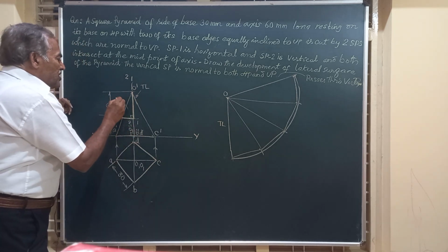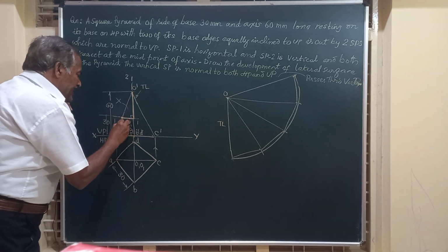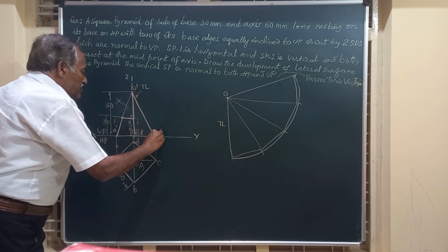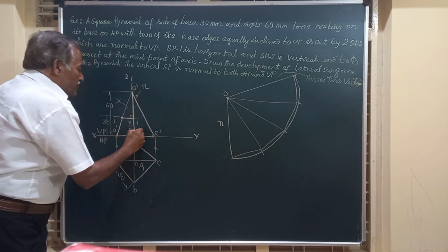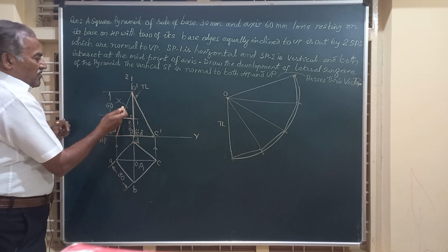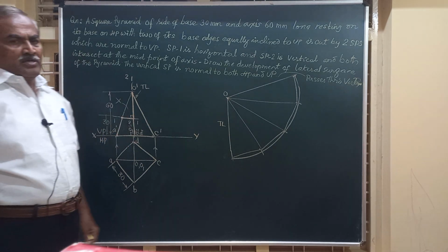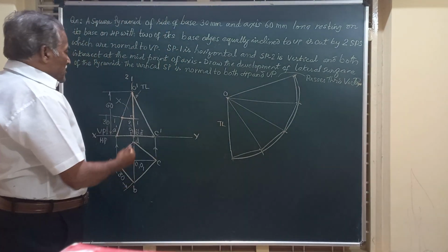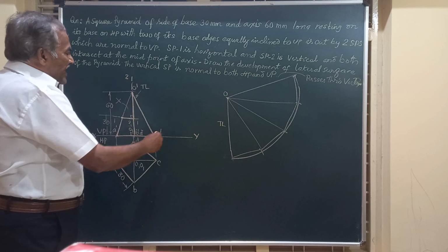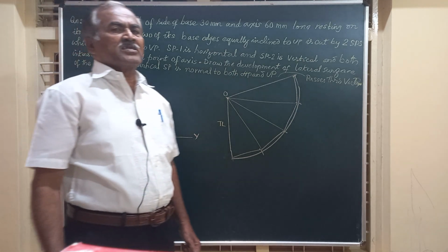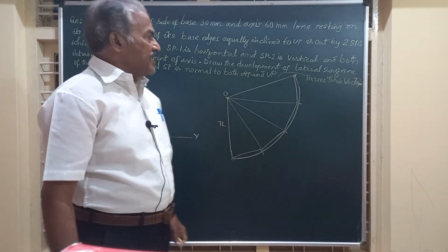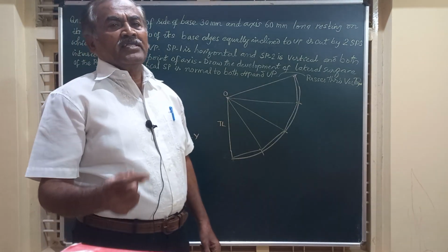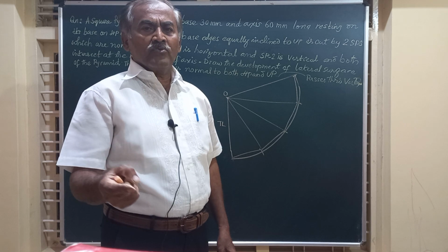So assume we are going to throw away this piece and retain the remaining part, which is going to be used for drawing the development. So this is the portion that is left over after this small portion is thrown out. Friends, if you observe the front view of the pyramid, you find none of the slant edges are totally removed after the section plane cuts the solid. And hence, you have the choice to start marking of this development either from OA, OB, OC, OD.